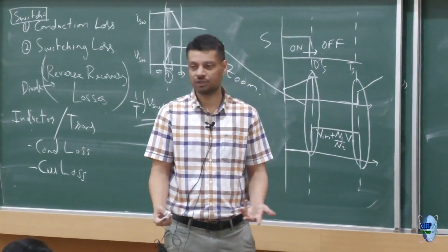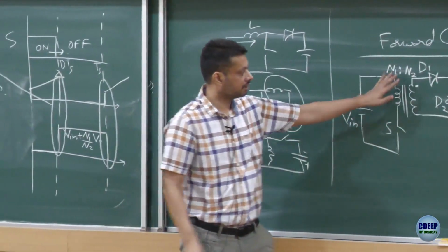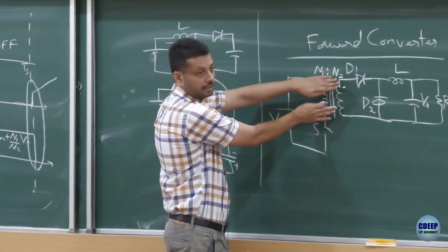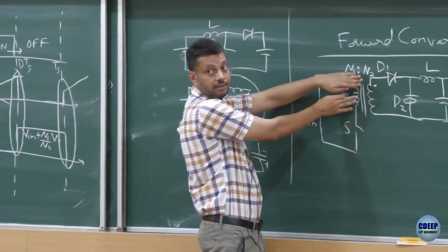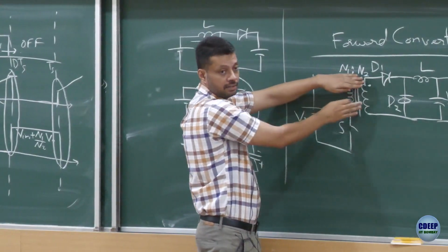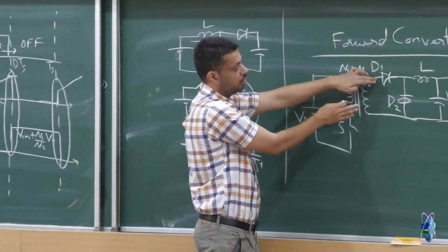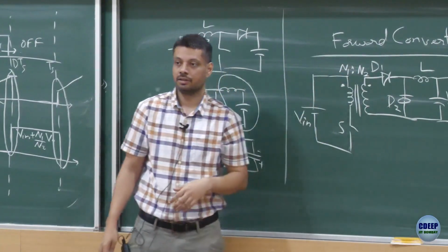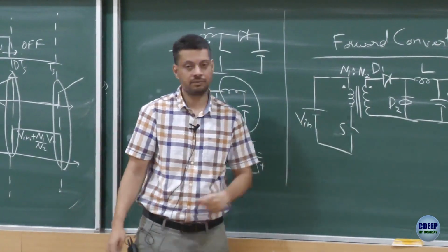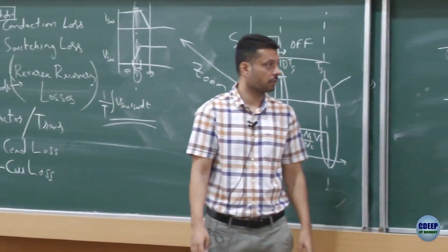So we still have to use an inductor somehow. You can see why I called it buck derived, because if you just look at this circuit, it looks like a buck converter at the output stage. Now instead of having a source here and a switch here, I have added a transformer based circuit, so that you can utilize the gain ratio of the transformer.